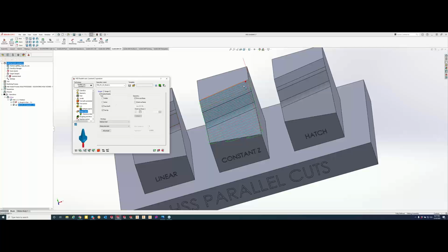And when it comes to a point where it's going to gouge that drive surface, what do we want it to do is basically what it's asking here. Do we want to retract the tool? We can do a trim and relink, which is one that I use quite a bit. We can stop the tool path calculation, as well as do a report so we can see what's going on with that gouge right there.